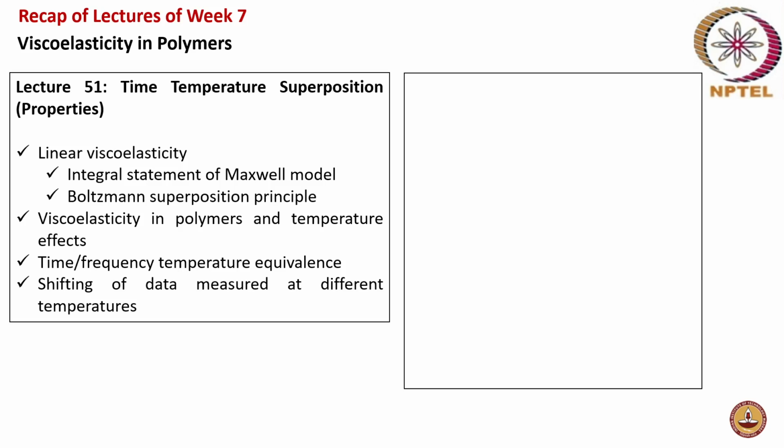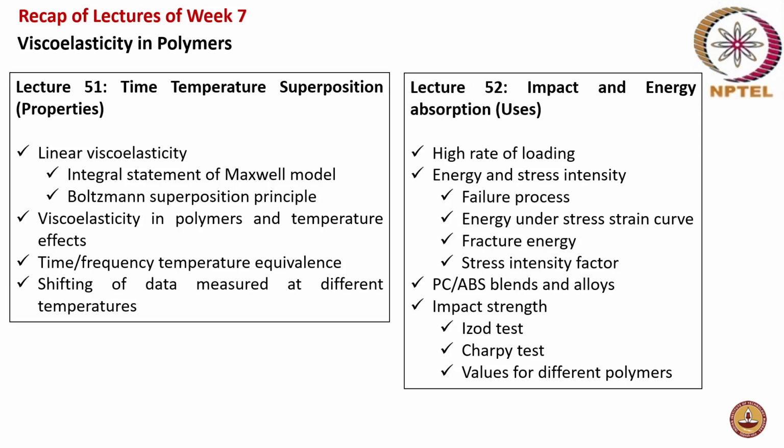Yes, ma'am. And the final lecture for the week was based on impact and energy absorption, where different types of loading were discussed. You know, low velocity, and then you had your impact, and then ballistic impact was all discussed, right? And then how the failure process starts, which is a combination of the material defects and also the molecular mechanism. It's a combination, right? And then energy under your stress strain curve, and then what is a fracture energy, right? What is fracture energy, do you remember?